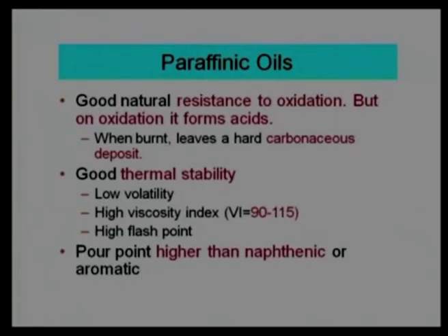So, lubricants are used to reduce friction and wear, but if we choose a lubricant which is not thermally stable, burnt at high temperature, the temperature may be 150 degree, 170 degree, 190 degree, then they will make deposits, and with the presence of deposits, the clearance will reduce. In addition, there is a possibility of these hard deposits to act as abrasion, wearing more and more.